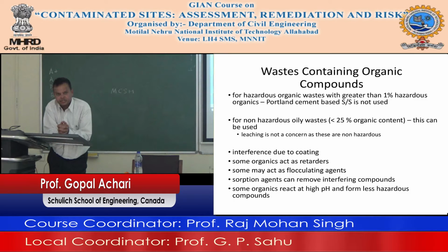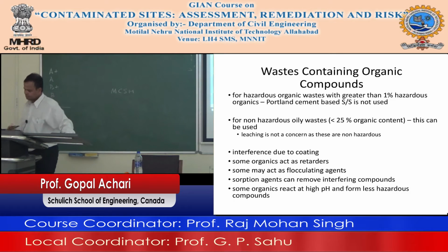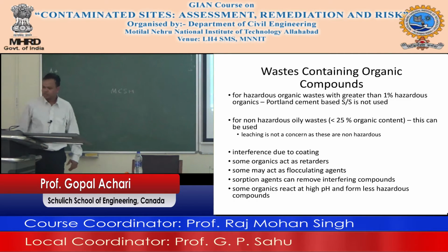That's bioremediation, right? That's a separate technology. But cement-based technology you cannot use if you have oily waste. There are two kinds of organics: hazardous organics and non-hazardous organics. If you have non-hazardous organics, you are not really particularly interested in fixing the non-hazardous material, so you might have a little more flexibility. If you have a hazardous organic, then you cannot use cement-based material.